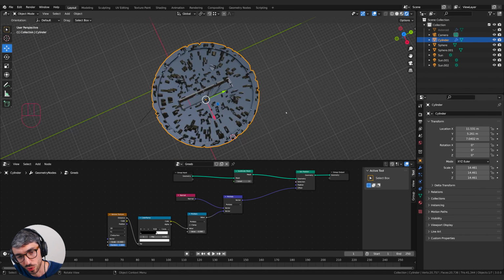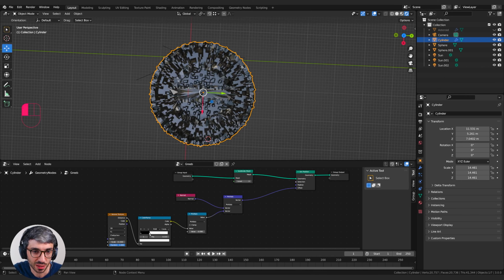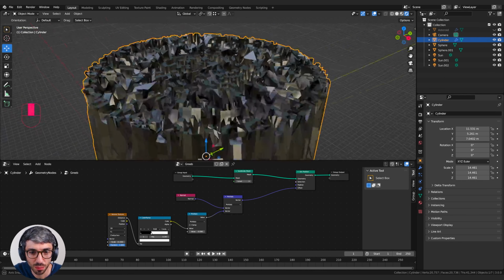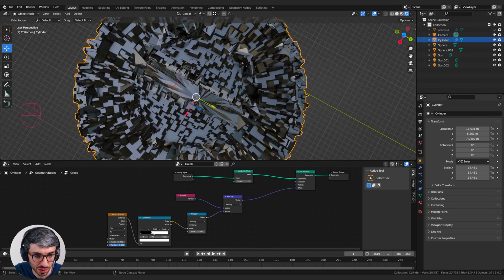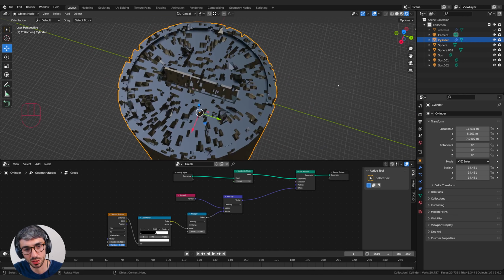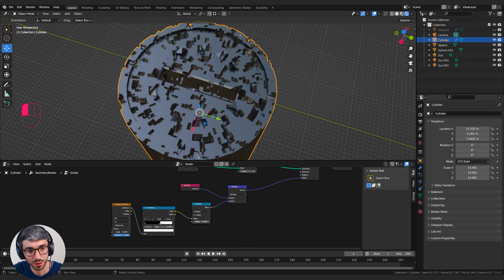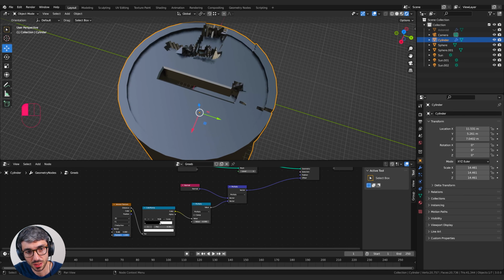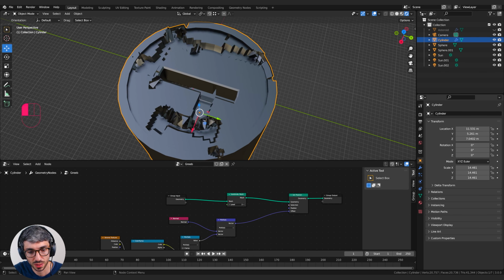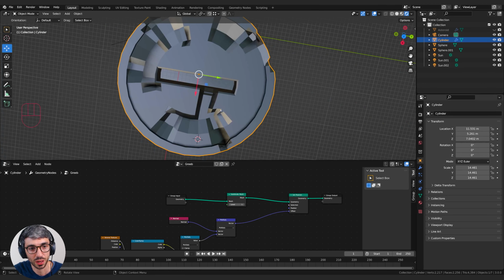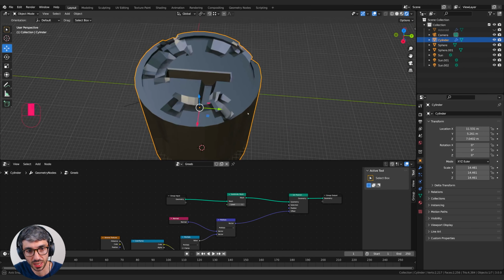All right, so it's not quite going to work the way I was hoping it would. I mean, it doesn't look great. There would be some applications for this, but this just looks like a mess. But we're still going to use it. We're still going to use something to create a cool shape. So I'm going to take my scale down, and I'm also going to take down my subdivisions, I think. So I'm going to take this down to 1. This will help clean up some of those jagged edges.